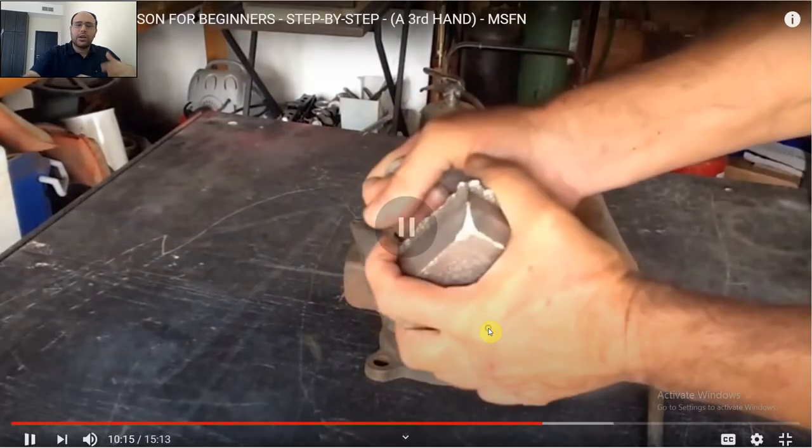So this is after-casting processing. We started by making the button, then we made the mold out of sand, then we melted the metal, then we poured the metal. So this is step 4, pouring the metal into the mold, leaving the mold for a while until solidification. Then breaking the sand to end up with the casting product. This is the 6th step, and the 7th step is just to trim the vent, or riser, and the sprue. And the 8th step is to do post-processing. Post-processing is to do machining.